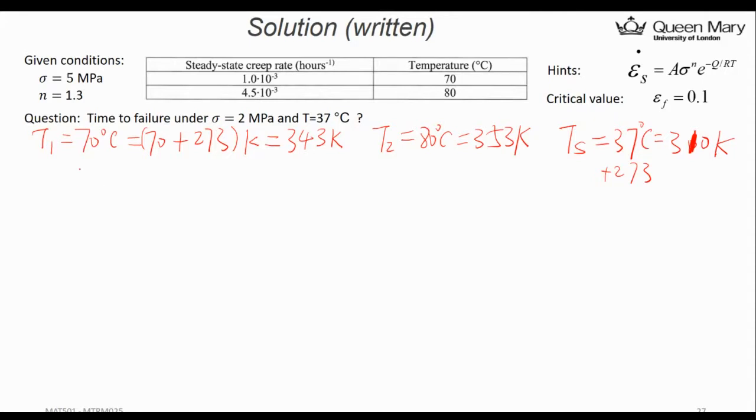Now, let's write this creep strain rate equation. What you know is the stress, sorry, this is not E, this is stress. For that table it is 5 megapascal. You also know the steady state creep strain rate, and you are given the temperature.